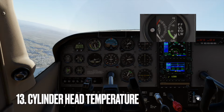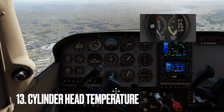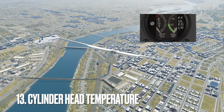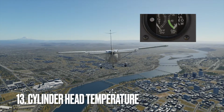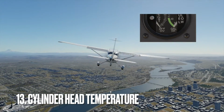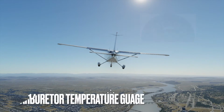For example, during climb, the pilot monitors CHT to prevent cylinder temperatures from exceeding maximum allowable limits. Proper cylinder head temperature management is crucial for engine reliability, performance, and longevity. An interesting fact about the CHT gauge is that it helps pilots detect engine anomalies, such as cooling system malfunctions or cylinder leaks, by monitoring temperature trends during flight.